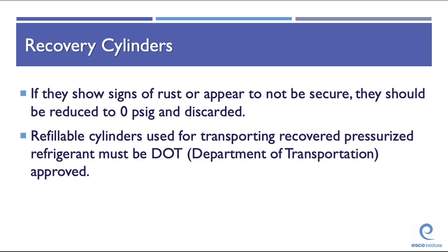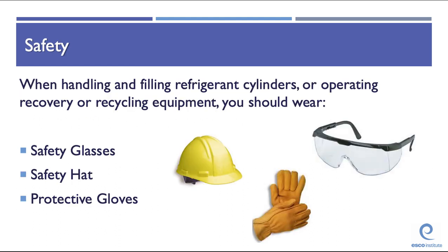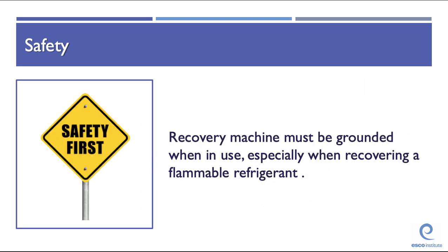You have to take a little bit of safety into account as you're working with it. The EPA is concerned not only with the prevention of refrigerant venting, but the technician's overall safety. When handling, filling refrigerant cylinders or operating recovery or recycling equipment, you need to wear safety glasses, protective gloves, and follow all equipment manufacturer safety procedures. Make sure the recovery machine is grounded when in use, especially when recovering a flammable refrigerant. You do not want any stray voltages.